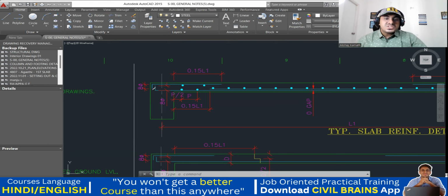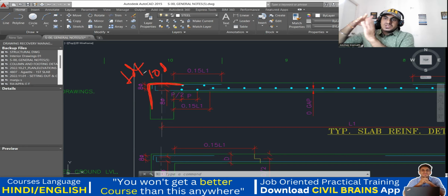Second, if you do the complete development length, like Ld plus 10D, instead of giving only a small development length, this much, at this junction, what will happen? Complete fixity will happen. Due to this complete fixity, whatever moments will come from the slab, all the moments will be passed on to the beam here.